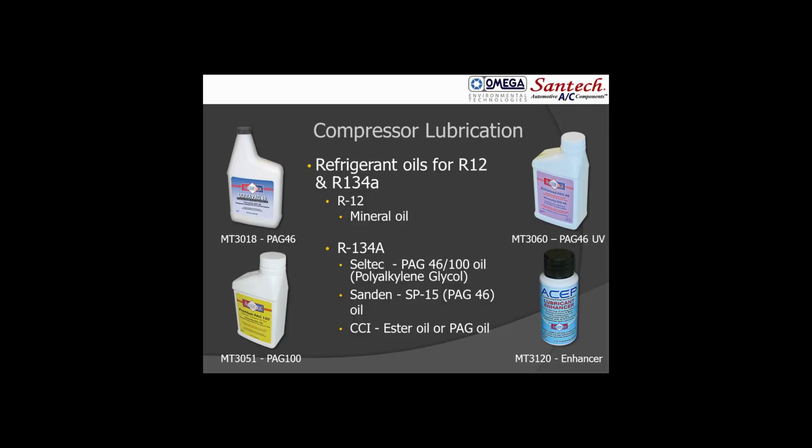And when you go looking for PAG oil, you'll notice that there's several different types of it out there. There's a PAG 46, a PAG 100, a PAG 150. As time has gone on, that viscosity number has gone down, where most manufacturers today are recommending and using generally a PAG 46 or a PAG 100, a little lighter weight oil. Because even in the wintertime, when you run your defrosters, you're still running your AC compressor, so you need a lighter weight oil that flows well, that will still lubricate that compressor even when it's cold.